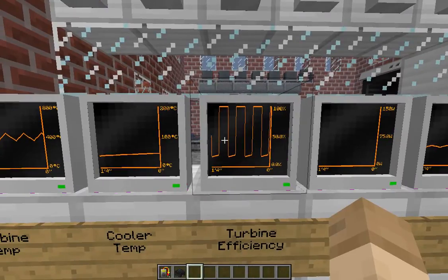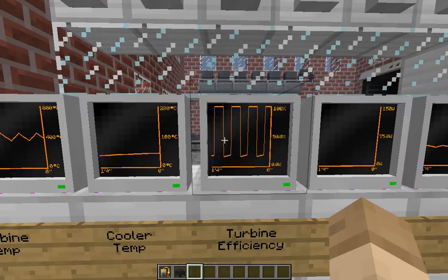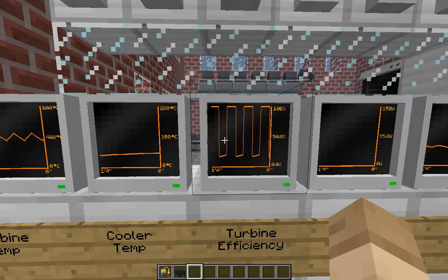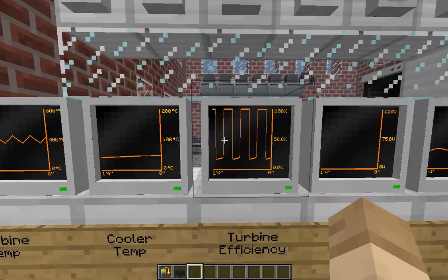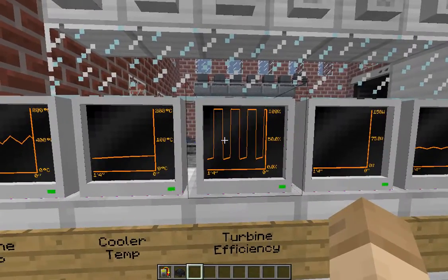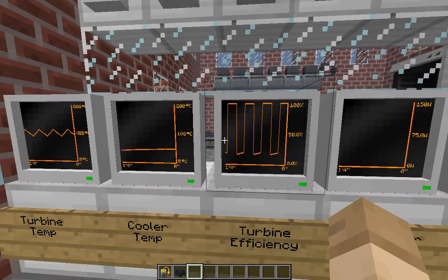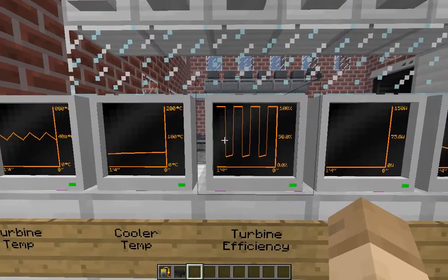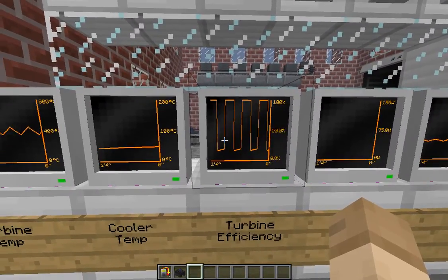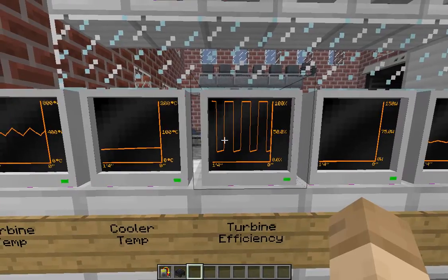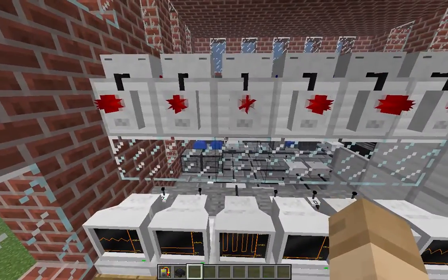If, however, you really wanted your voltage to be 225, and you regulate your system between 223 and 227, and all of a sudden it produces a bunch of power, hits 223, starts winding down, and then hits 227, because of that extra amount of heat left in the furnace, you're going to overshoot that 227, and with the way the voltage regulators work, it will actually cut off all power to that system, effectively eliminating that section where you have your furnaces running constantly.